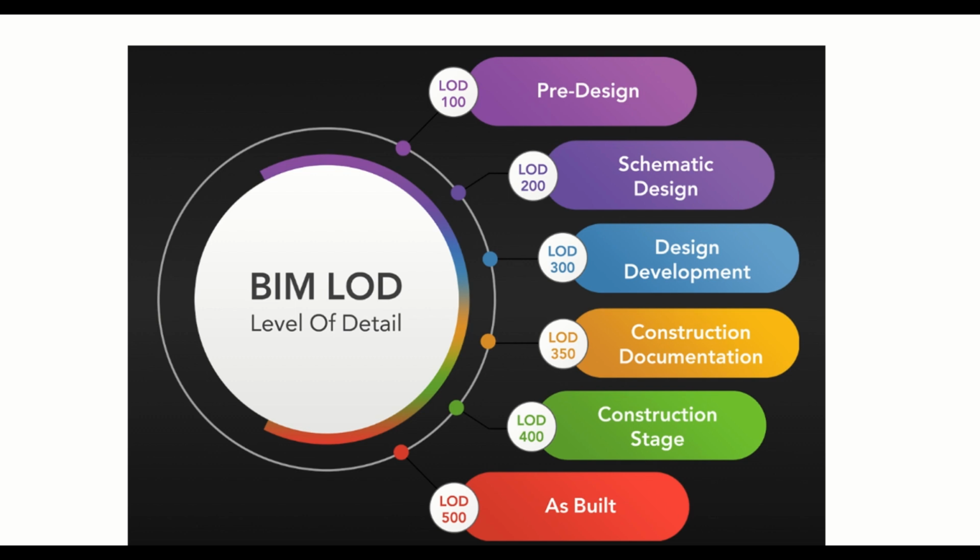Okay, the hanger will be shown, and the hanger is not just a hanger. Every channel will be shown. All the connectors will be shown, the nut, TLB, and all the twist locks if needed, the base connectors, the anchors. All the details will be given on the sheet with the proper marking. For example, this is MCS01 support, this is MCS02 support, like that. Every detailing will be given at LOD 400.